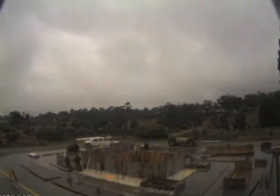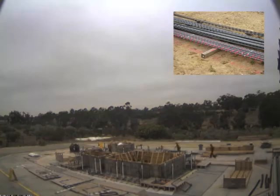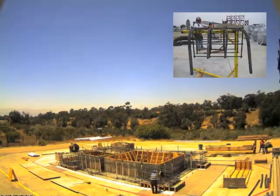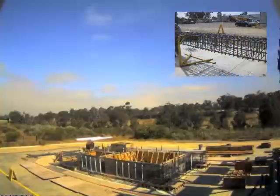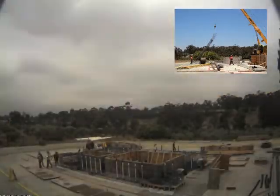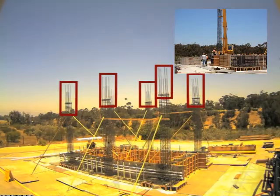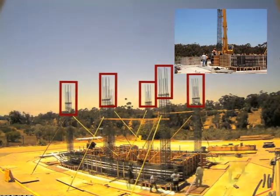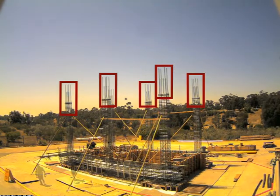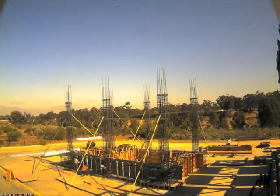Continuity with the superstructure is facilitated by extending reinforcing steel from the foundation with sufficient overlap to reinforcing steel provided within the structural components, such as walls or columns. In this project, during placement of the foundation reinforcing cage, the reinforcing cage from the columns were placed and extended well into the upper levels of the building. The columns were detailed with a prefabricated welded tie tightly spaced up its height, encapsulating the vertical bars.